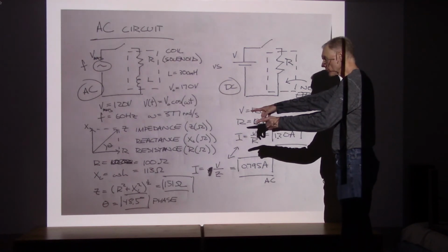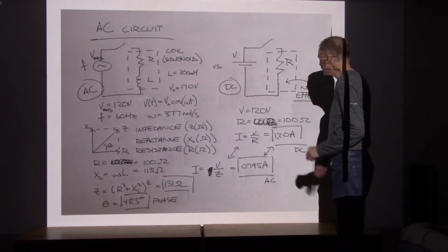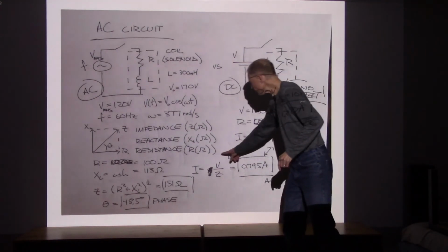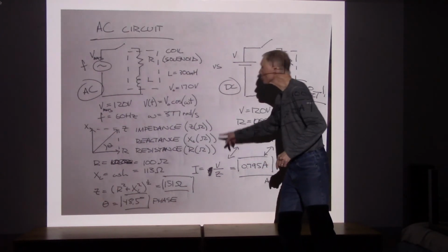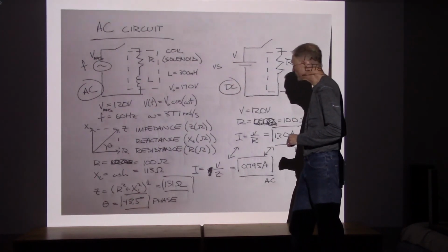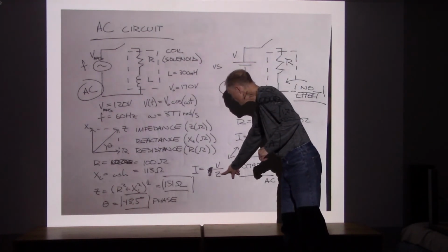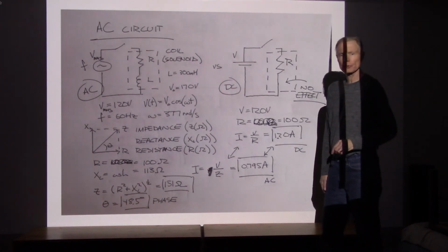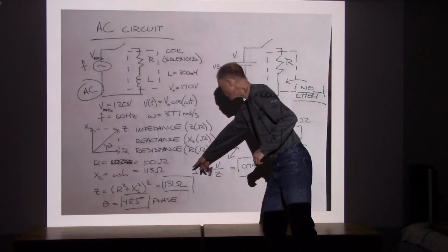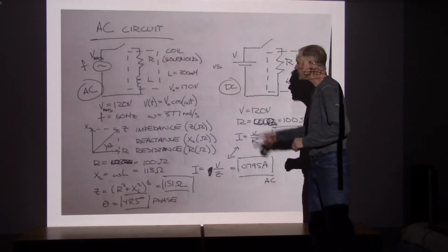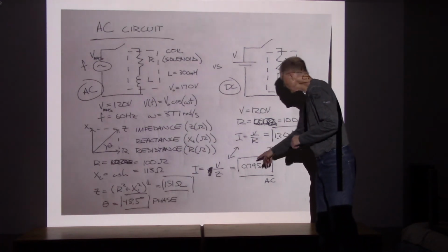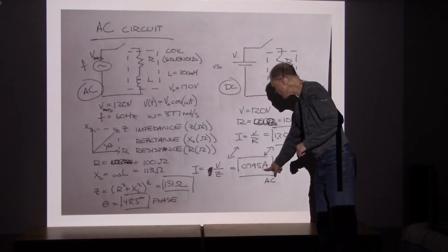we've got all of the impedance determined, and now what we do for AC circuits is we take the total voltage, which we were saying was 120 volts, that's an RMS value, and divide that through by the overall resistance. And the overall resistance here is the 151 ohms, and that says in the AC example, I'm only going to get 0.795 amps.